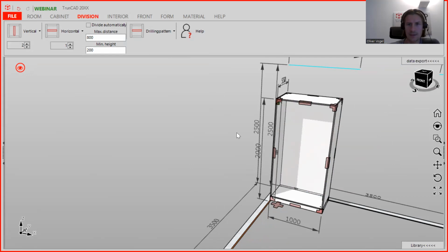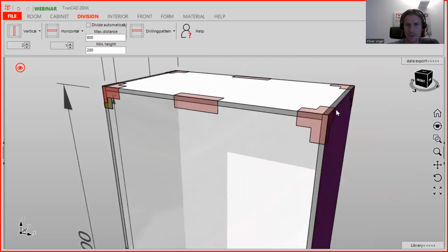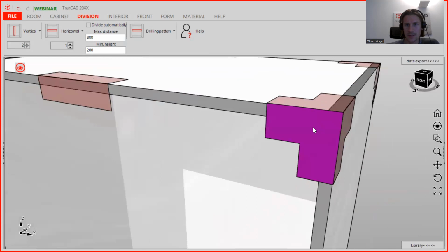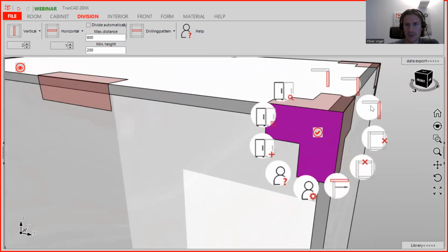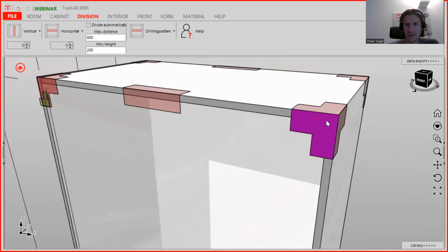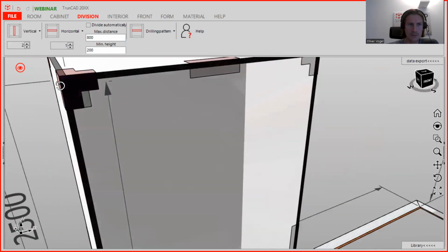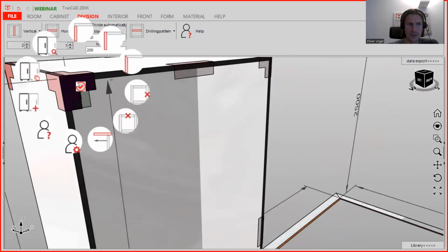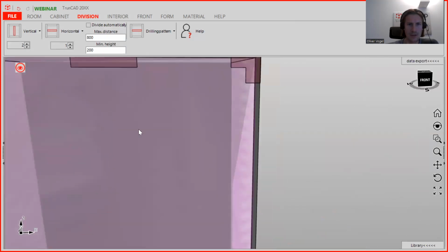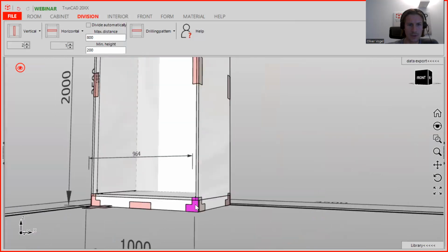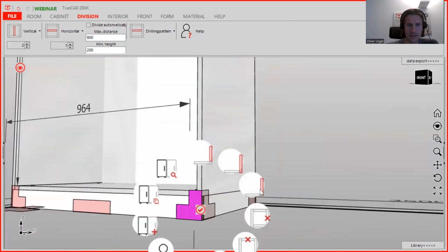Now you can set your back panel to miter, and therefore first of all you need to set here all edges to miter. You see they are in a default setting, going to the top panel and the bottom panel, and we change this to miter for all sides.